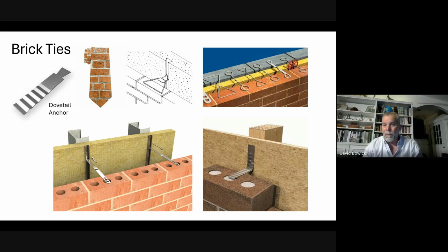And the brick, now you have to make sure that you match your mortar joints. Your mortar joint for your block has to match your mortar joint for the brick. Not that inconvenient, because the height of a block is 3 brick courses, which is very standard. So almost always that's the case, unless you're into an oversized brick. So making sure the mortar joints align is actually not problematic at all.